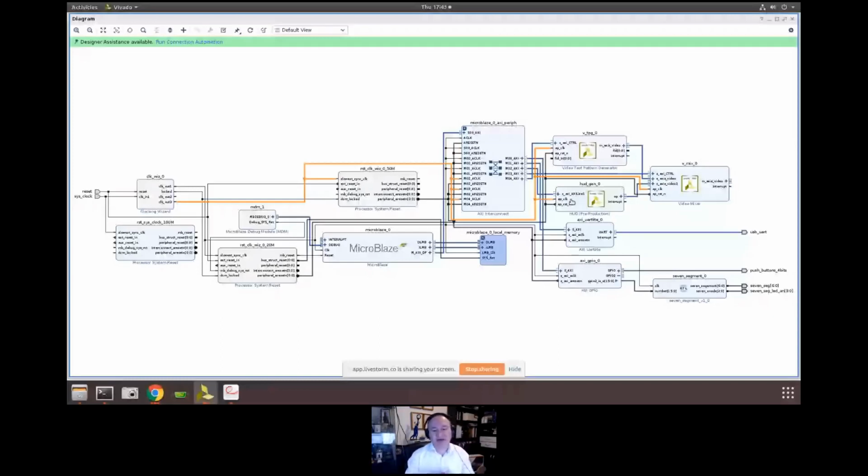The test pattern generator is going to give us the background. So we've got a nice background, and in the example video I showed, I've got the color bars, but you could have a red, black, white, or green background. You could have a different pattern background if you wanted to, just to make it a little bit more interesting. And then we've got this AXI video mixer here that's going to mix the 2 video layers together and put the heads-up display on top of the test pattern generator, such that you can see the ball and the bat as it moves about.